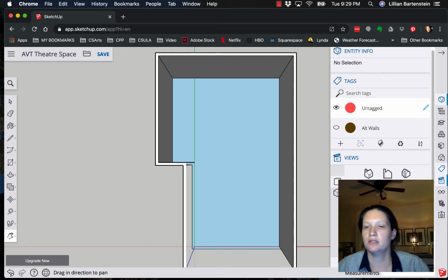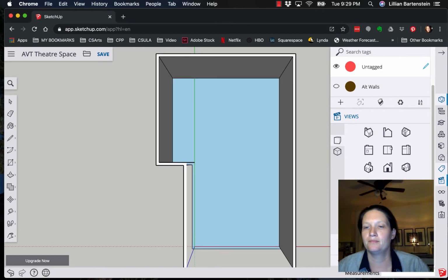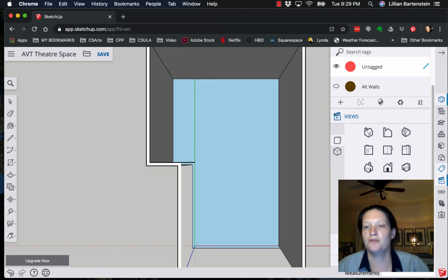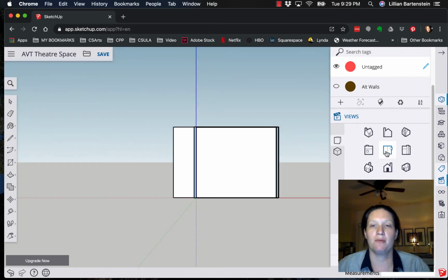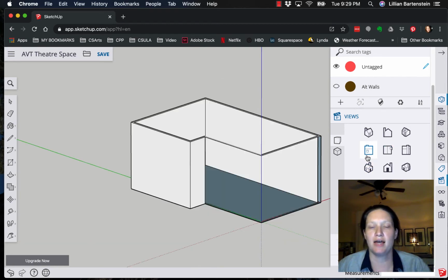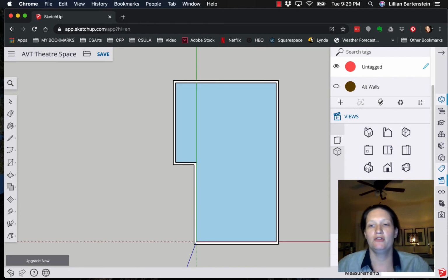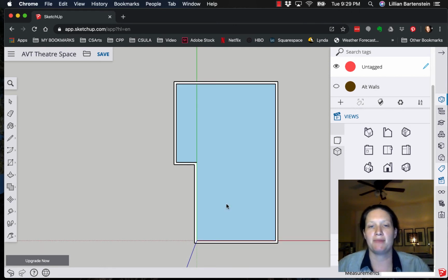There are no scenes in this model. I want it to be not that setting. I don't know. So field of view. If I drop it down to 1, now it does look like a straight up orthographic projection. If it's easier for you to understand your drafting that way, which it is for me, you just change your field of view all the way down, right? When it's 35, you're getting that 3D mode. When you drop it all the way back down to 1, it's now just a straight up orthographic top view, which is what I wanted.